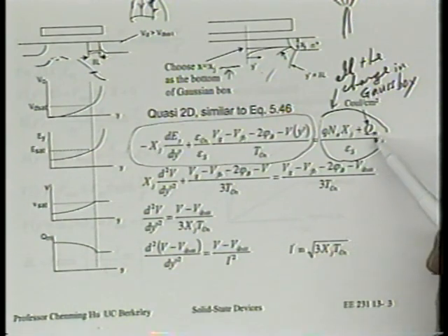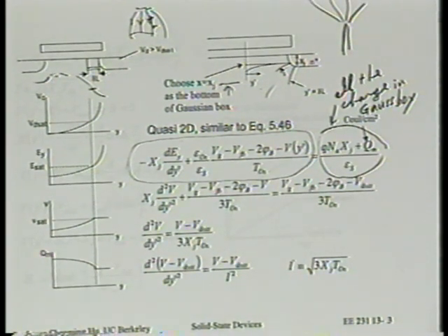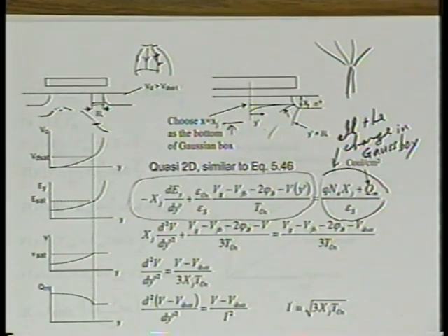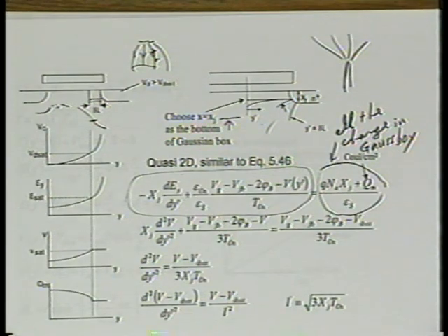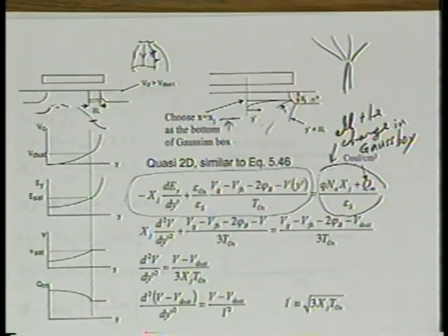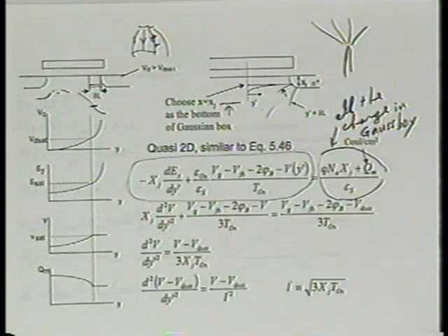The next charge is even more interesting and very clever. You see, the problem we solved for the drain-induced barrier lowering, we implicitly, maybe explicitly, assumed we're dealing with the subthreshold region. Is that right? In the subthreshold region, VG is less than VT, or maybe just equal to VT, if we use that to model delta VT. Therefore, do we have a large current or not? We don't have a large current. If we don't have a large current, do we expect to have a large density of mobile carriers?